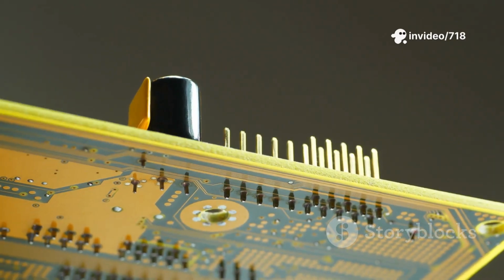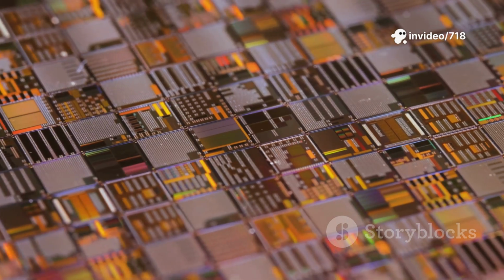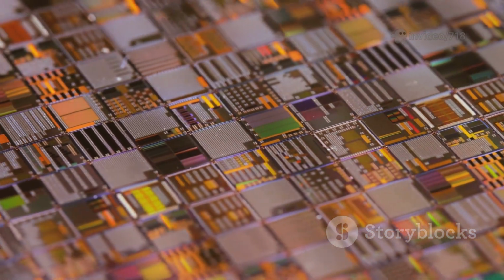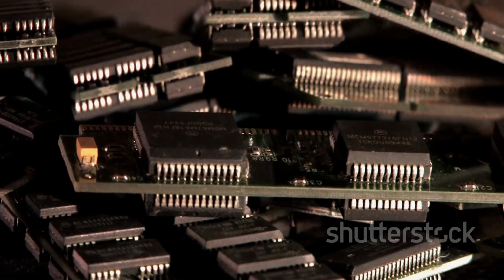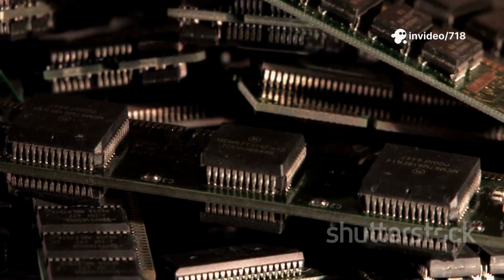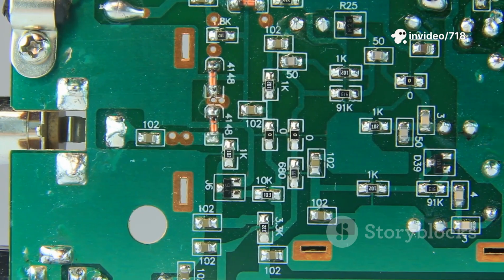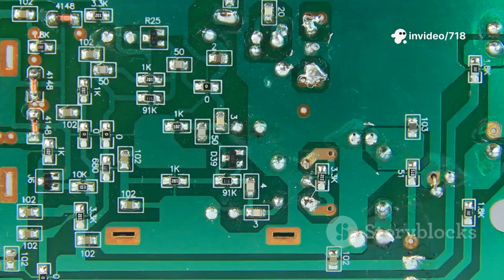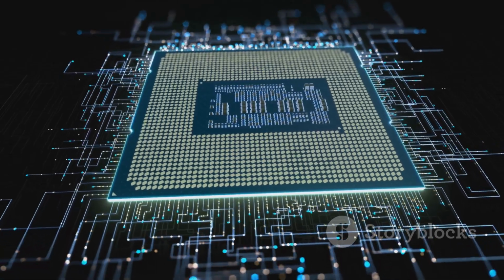Dennard's 1T1C design was the epitome of engineering elegance and efficiency. It was incredibly simple, which meant that you could pack an immense number of these cells onto a single piece of silicon. This directly addressed the biggest problem of the time: density and cost. By reducing the complexity from the 6 transistors required for an SRAM cell down to just one, it promised a future of high-capacity memory at a fraction of the cost.